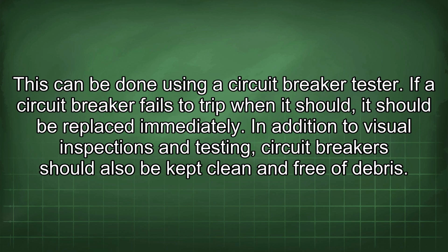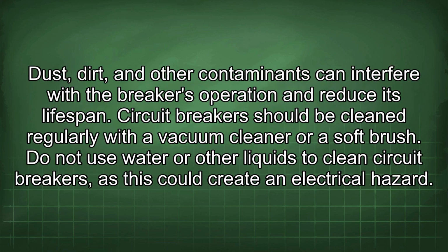In addition to visual inspections and testing, circuit breakers should also be kept clean and free of debris. Dust, dirt, and other contaminants can interfere with the breaker's operation and reduce its lifespan. Circuit breakers should be cleaned regularly with a vacuum cleaner or a soft brush. Do not use water or other liquids to clean circuit breakers, as this could create an electrical hazard.